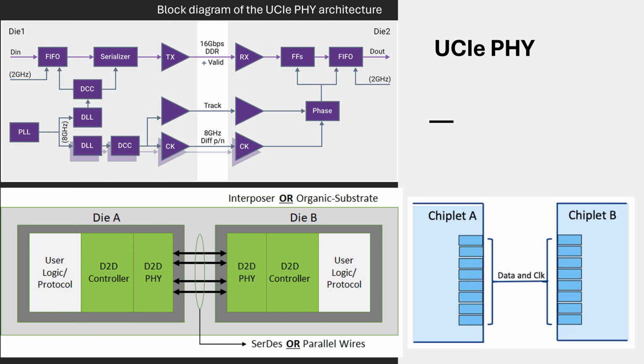In addition, we might need clock circuits of different phases. We might need additional equalizers, left and right. We might need power supplies. Many other things are required here. Otherwise, that is a simple block diagram of the UCIe PHY, in other words, the SerDes.